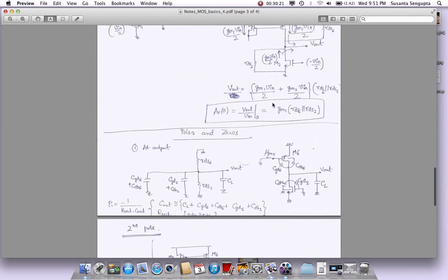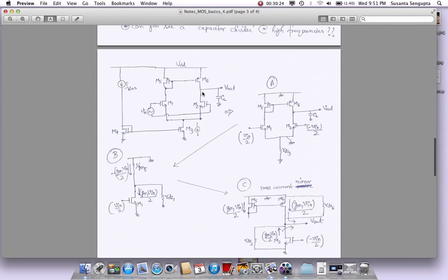So we have solved this amplifier now to find what is the DC gain and what are the approximate pole and zero locations. Okay, and what the Bode plot looks like. So hopefully now you have seen a few examples of amplifiers, and you can extend this to other circuits that you have in the textbooks. Again, I would like to stress that please do the derivations of the complete small signal model to understand it, and these intuitive techniques that I'm trying to show you here give you 90% accuracy results. They won't give you 100% accurate results, because for that you have to do those derivations.